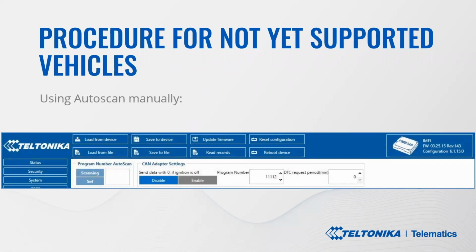Another way to proceed with auto scan is simply connecting to the configurator. After connection is done successfully, you can launch the configurator and navigate to the CAN adapter tab. Of course, before clicking the scan button, make sure that the ignition is on and the ignition source is configured to digital input 1 or power voltage.